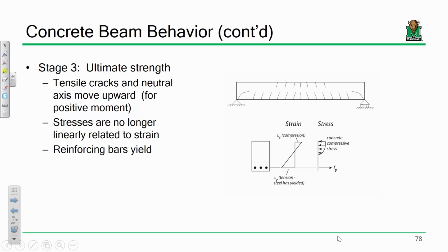No matter what stage of behavior we're in, we assume that the strain always behaves like that. In other words, here it is before I apply the load, and here it is after. And it's still straight, and it's still perpendicular from the centroid. So if you were to track the centroid, it wouldn't move at all, and as you got further away from the centroid, it deforms more and more. Make sense? Okay.